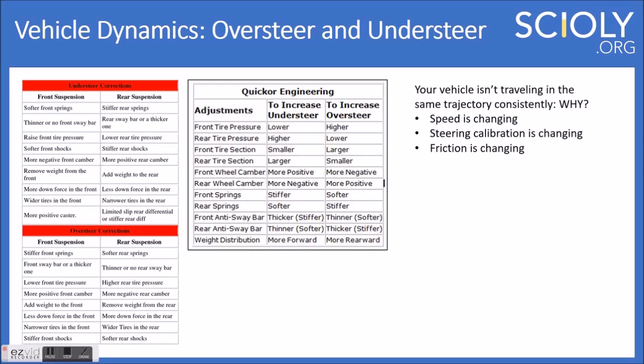So that could easily be another reason. And then from there on, we stopped using belt conditioner to clean our wheels. We went back to water just because we didn't want to see such inconsistency. So even though it was getting better acceleration and stuff, we wanted to make sure that whatever results and data we were collecting was consistent, and we'd be able to repeat this at tournaments. So watching out for the speed, these three things that are listed here are huge factors if you're having problems with your trajectory. These are things that you should look at.